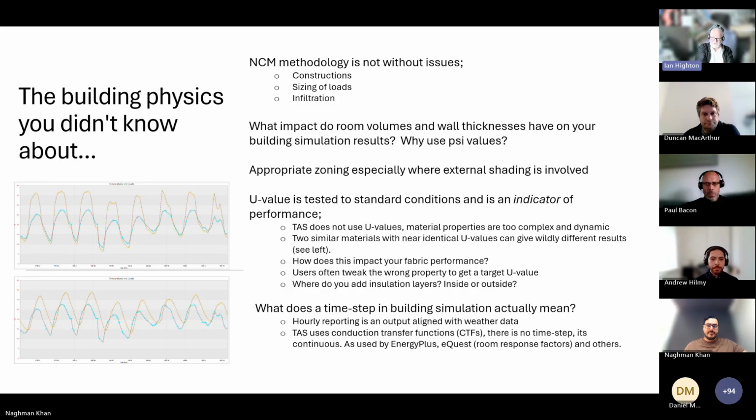The insulation on the outside is just light years better, because the inside space has got access to that thermal mass. So that's a really good test if you want to do a very quick and simple one. Insulation on the outside or insulation on the inside on a simple concrete cube, you'll see a very rapid difference. Yeah, marked difference, and yet it's the same U value.